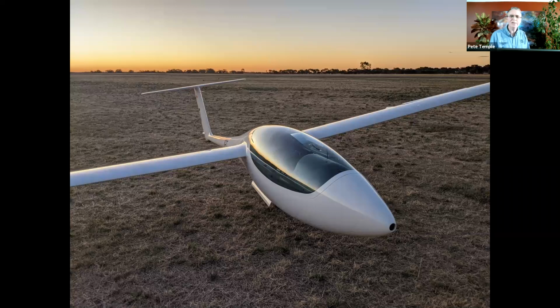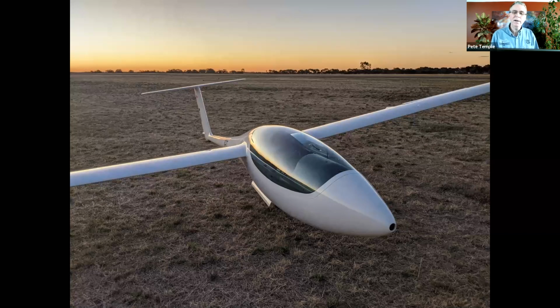He devised a theory as to what the optimal speed we should cruise at is, based on the strength of the next climb. So when we're flying, we're nominally flying a McCready setting, which is based loosely on our next climb rate. That's a fairly old school way of planning our speed, and I don't tend to use it very much these days. I was mostly cruising at a more or less fixed speed of about 90 knots, a little bit slower if I was in rising air and a little bit faster if I was in sinking air, which probably equates to about a McCready 5, something like that, for the glider pilots.